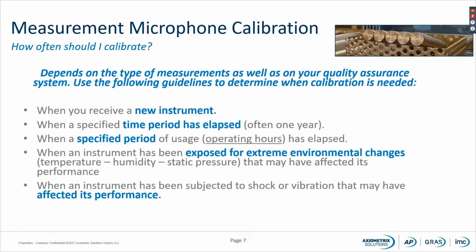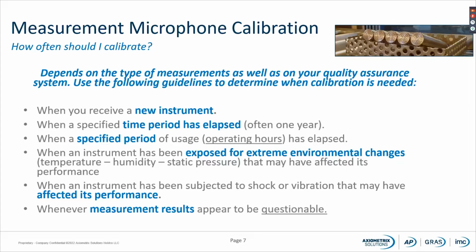When an instrument has been subjected to shock or vibration that might have affected its performance, it's also a good idea to do a calibration. And whenever measurement results appear to be questionable, it's also a good idea to do a recalibration of the instrument.